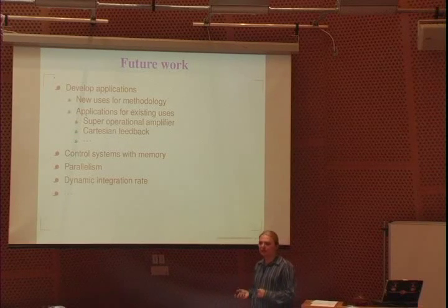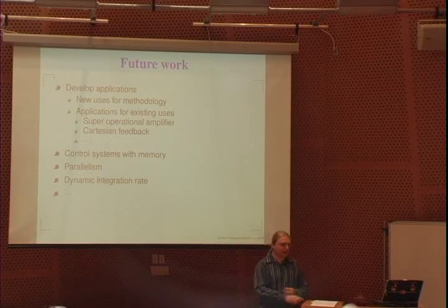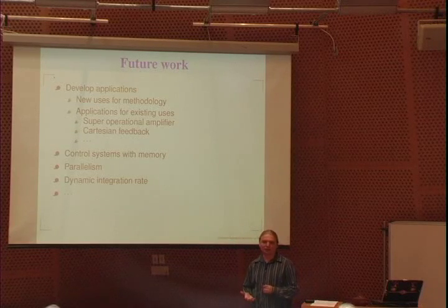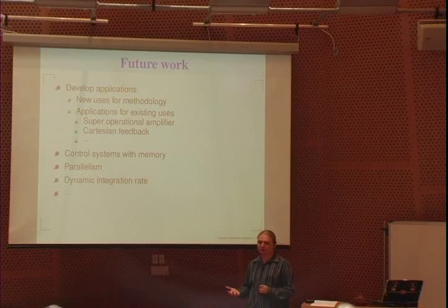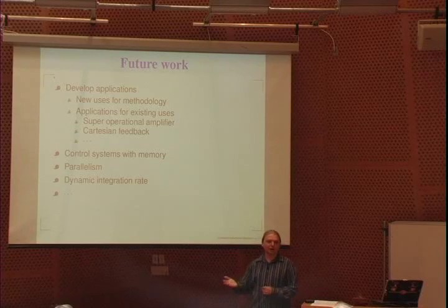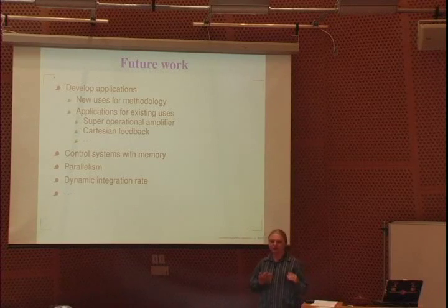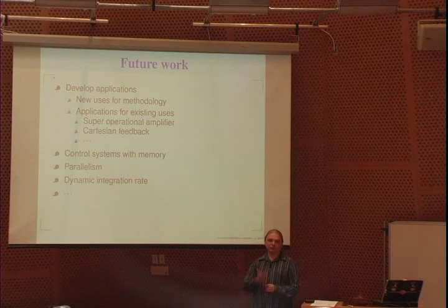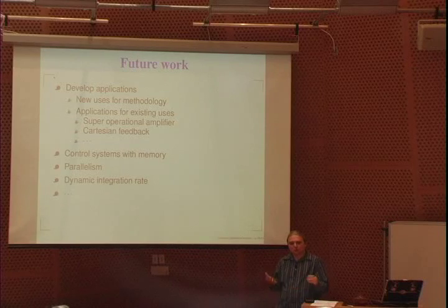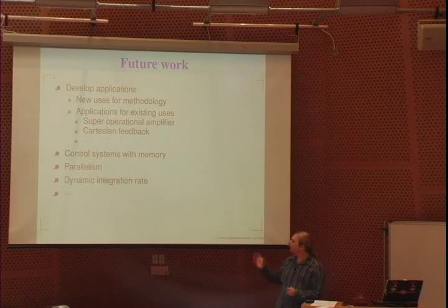This looks like it has applications to controlling a nonlinear system with a time delay, if you're trying to compensate for the nonlinearity as opposed to a disturbance. If you do this with a traditional feedback loop, it's a hard problem; you're fundamentally limited in feedback loop performance because of the delay. If you build a model of it, it works a lot better because you don't run into that limitation.